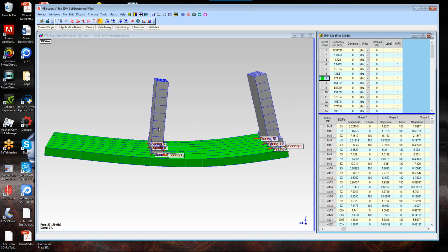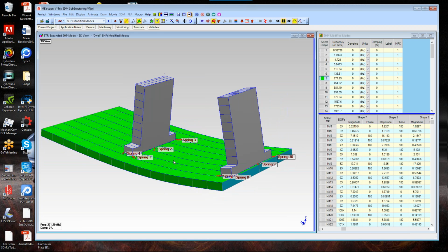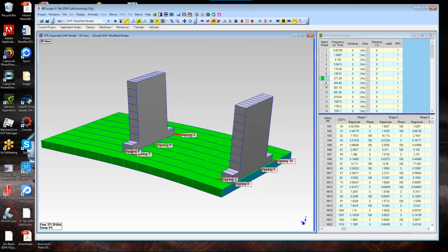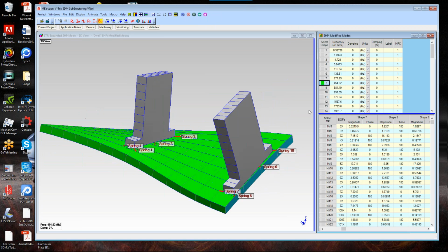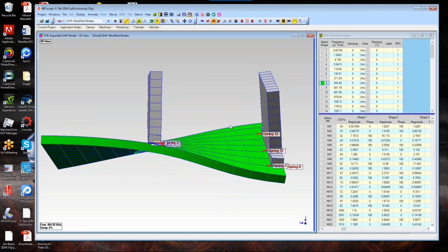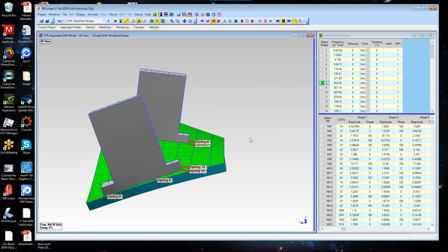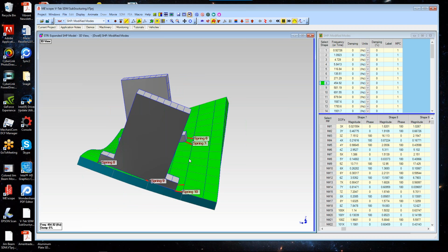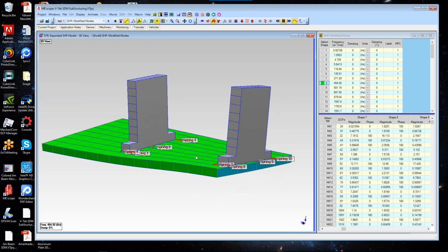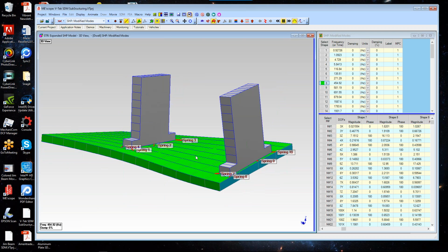There's our first real flexible mode, bending of the bottom plate and the bearing blocks just moving with it. Here's our second mode. It's a torsion, but not completely symmetric because those bearing blocks, including their weight, are all being modeled here correctly with the modal model. So another term we use with SDM is that we've started out with a modal model of the 3 substructures, and SDM has modeled the attachment of each of the substructures.